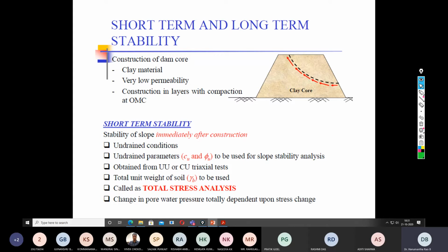Often you may see that many people are simply conducting the UCS test and using the value of Cu, but which is not true. So the UCS will always give you the least possible shear strength of a soil. It is only an indicative test.